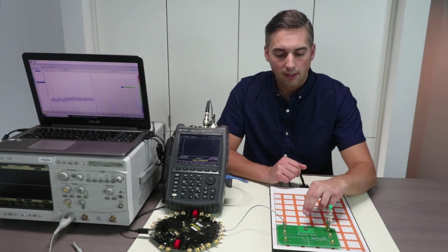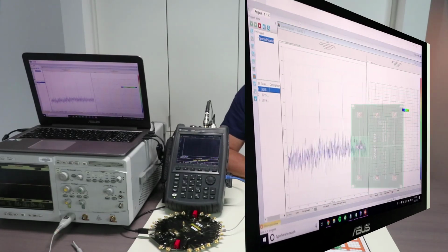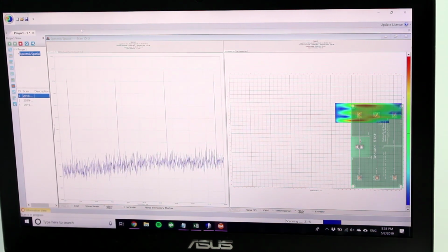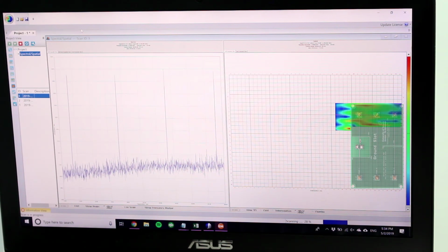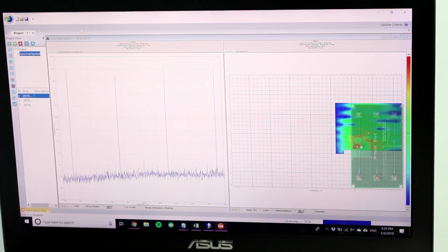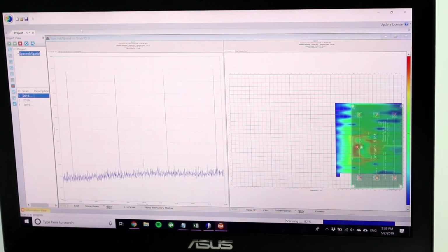Okay, now we're going to run this again, and I'm just going to press these two buttons, which essentially shorts the ground plane on both sides of this, so it's predominantly bypassing the loop that we created. One is a short, the other one is capacitively coupled, so it's essentially two connections from either side, which allows the return current to flow on a much more direct path.